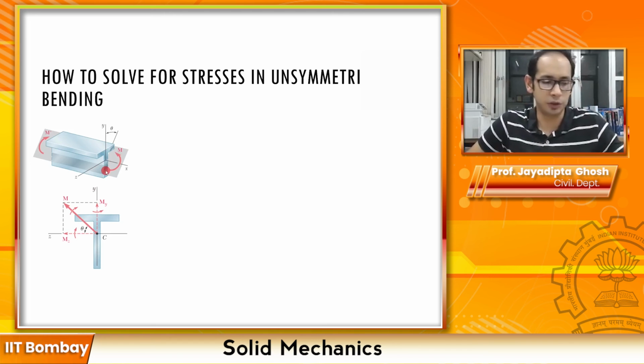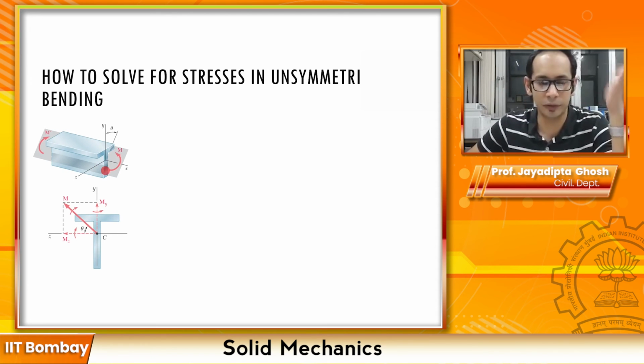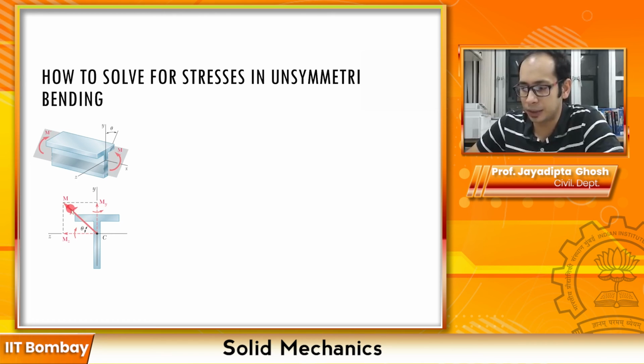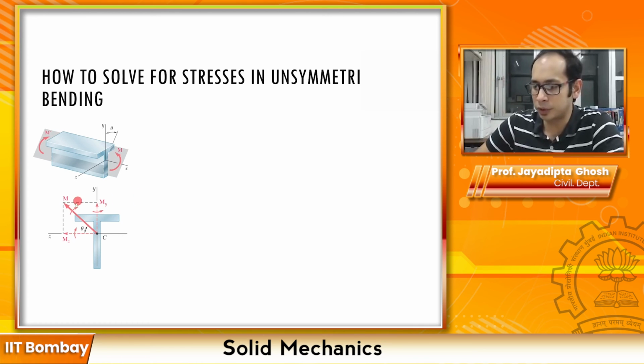The one which I was showing you with the styrofoam is a rectangular section, but as you know, the formulations we have derived are valid for any prismatic section. So now if I have this moment, this is the symbol for the moment. The moment is acting about this particular line over here. Again, this arrow is the thumb: where the thumb points, your fingers are curling over it.